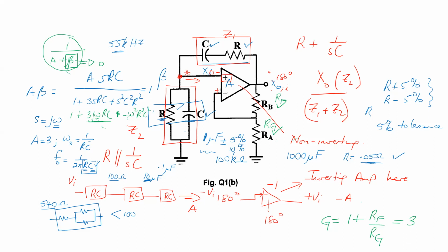So it's a number of things. You analyze the circuit from a practical standpoint. Let's say it was a lab exercise, and at the end of the lab exercise you had to give me an oscillator that was giving 100 kilohertz. First off, you have to analyze the circuit and get the oscillation frequency. You pick the capacitor value, you calculate the resistor value. That is going to solve the 100 kilohertz part.